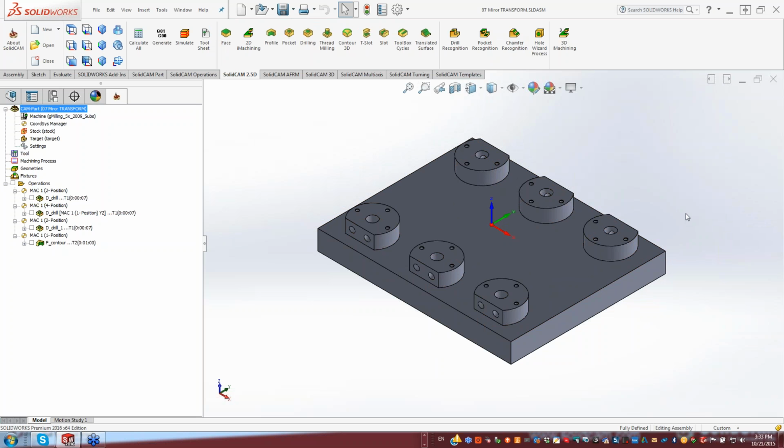That would be the problem. However, the toolpath, if you were working before in climb cutting, when you did the mirror, it would change over to conventional, go in the opposite direction. What we've added now with the new mirror function is that it actually mirrors the geometry but keeps the same direction as far as machining, as far as climb cutting.